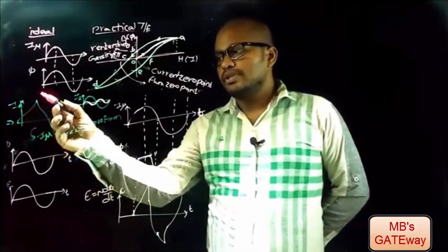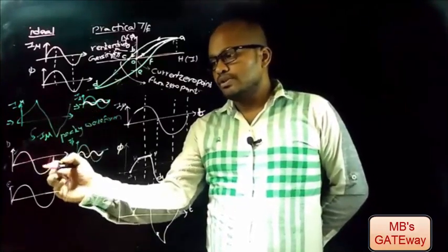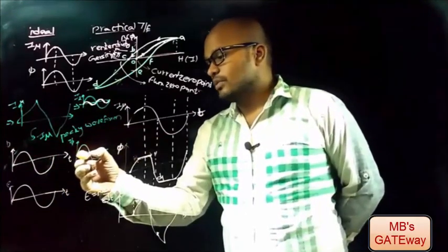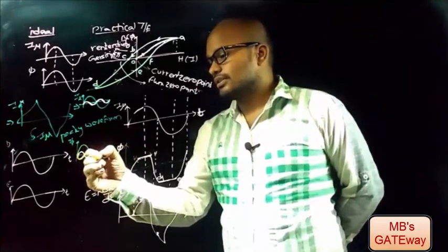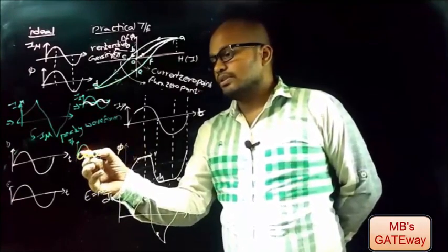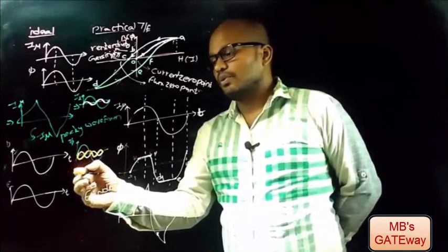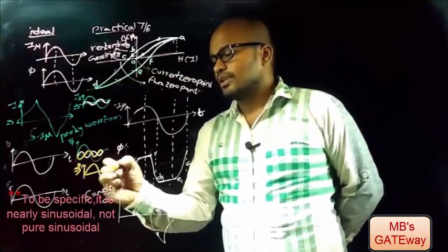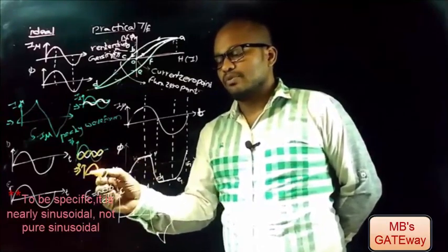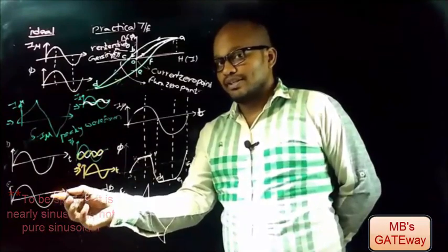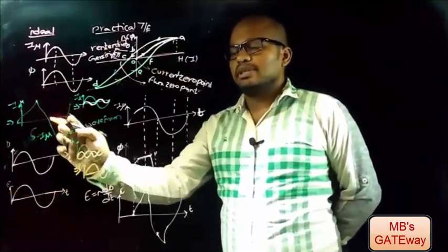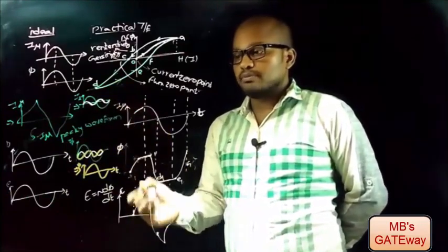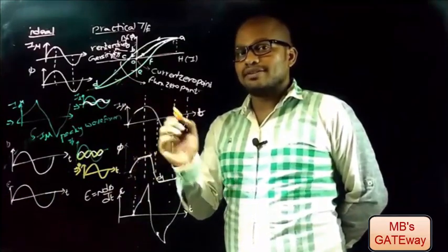But if you observe that with this non-sinusoidal input we are getting sinusoidal flux, it means these third order harmonics are not present, which means the transformer adds a harmonic like this, by which this and this will get cancelled, and the only waveform that remains is pure sinusoidal flux, by which we are getting pure sinusoidal induced EMF. But practically this peaky waveform is very difficult. So we need to think of how to get sinusoidal induced EMF with sinusoidal magnetizing current as input.